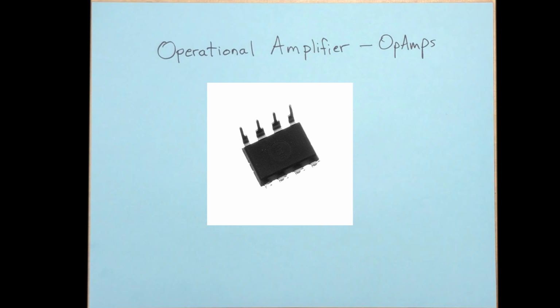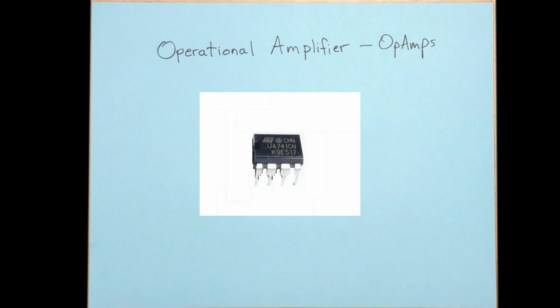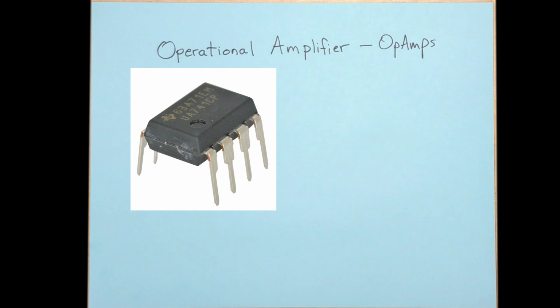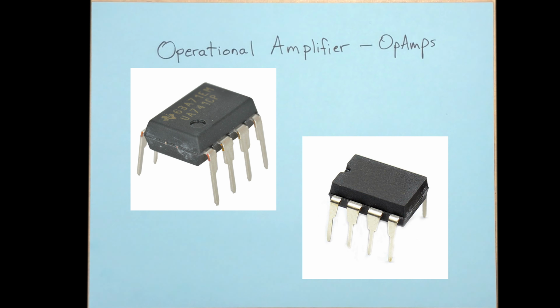So if you look on the top from above of each one of these circuits, you'll see there's some kind of indicator as to which way to orient the chip itself. If it's got a circle, you put that circle in the upper left-hand corner. If it's got a little divot, then you turn it so that that's at the top.